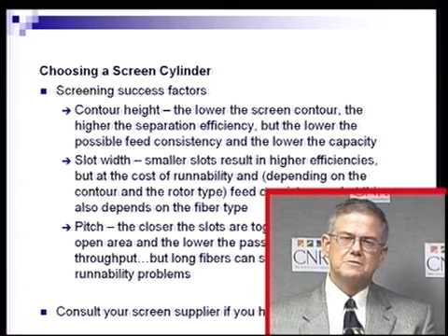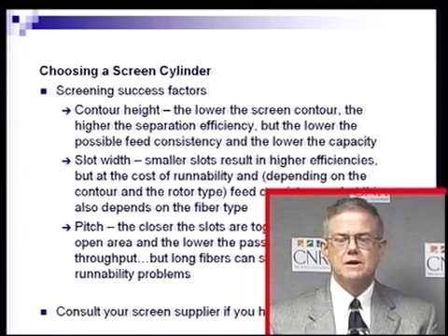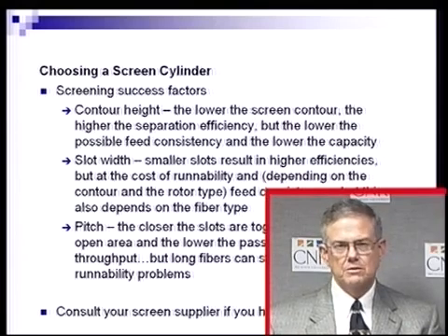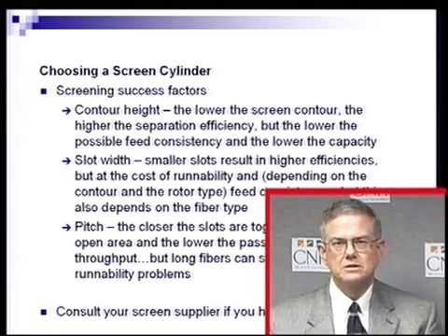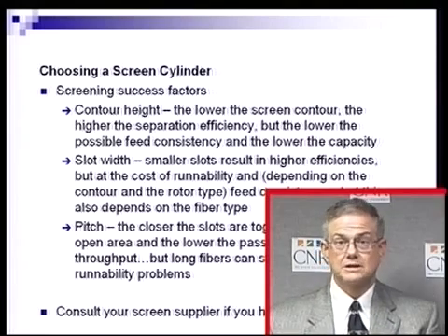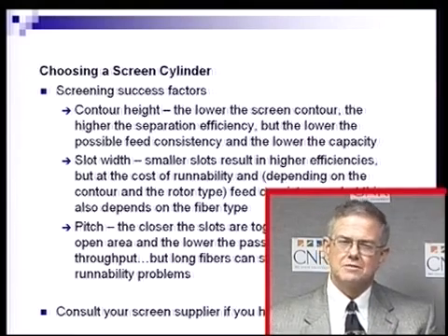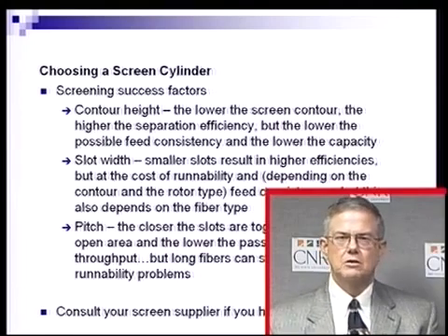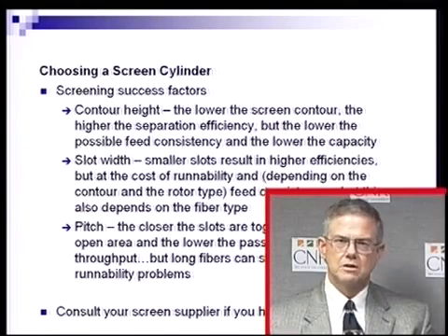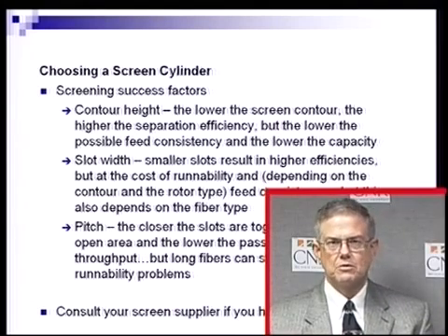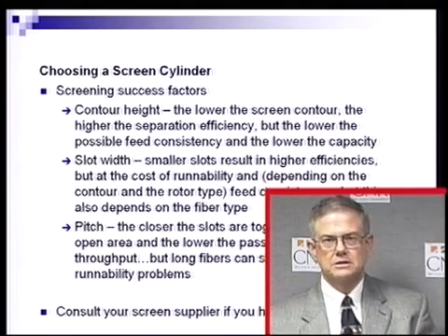The problem is that if we get them too close together, then we have hydraulic interference between one slot and the next and the following slots, and we actually lose capacity by having more slots per inch. So you have to play with this parameter as well, along with the profile depth and the slot width, in order to get a screen that performs suitably in your installation.